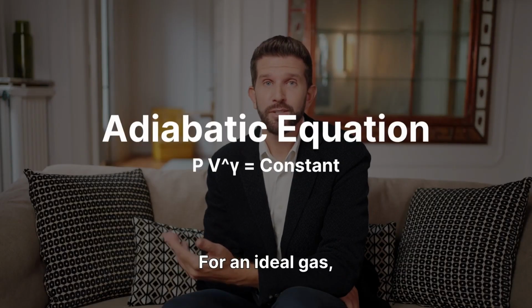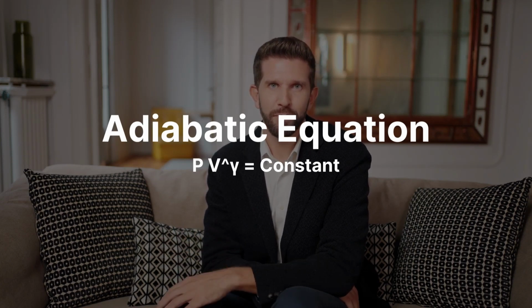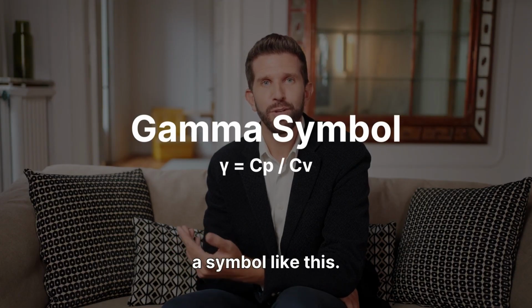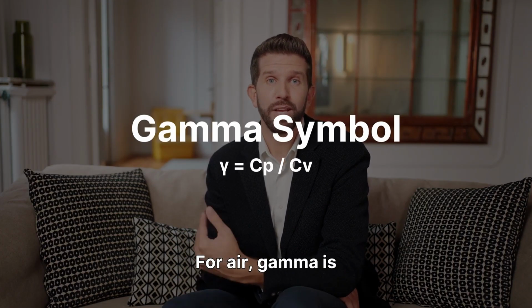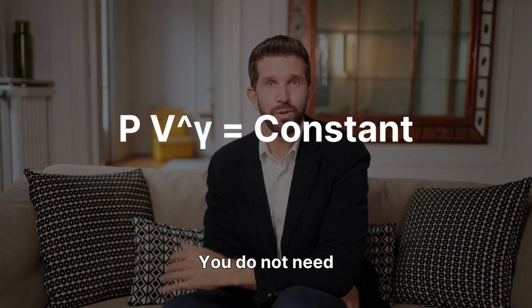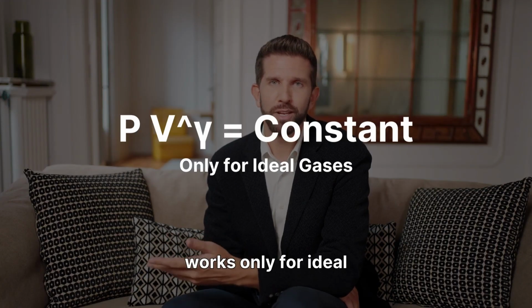For an ideal gas, the main adiabatic equation is PV to the power gamma equals constant. Gamma is written as a symbol like this. Gamma equals Cp divided by Cv. For air, gamma is about 1.4. You do not need to memorize numbers now. Just remember this formula works only for ideal gases.